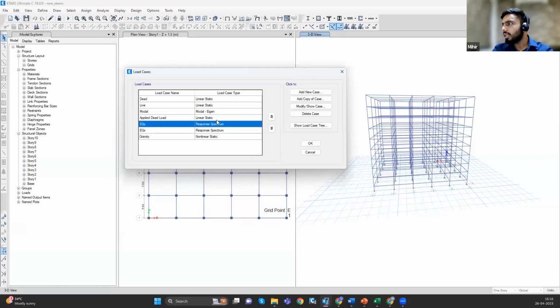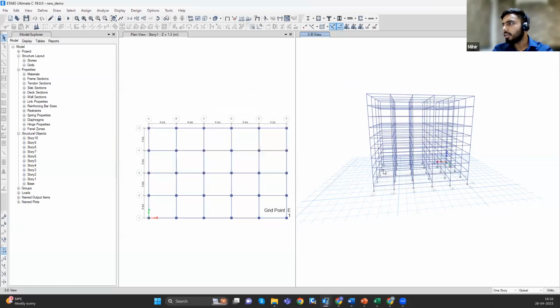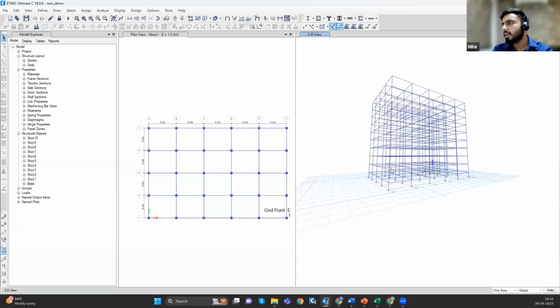So as of now, for the earthquake forces, I believe these columns are not passing, but I will move ahead for now. This will be an iteration process. We need to check how the structure is behaving, and accordingly we will update the member forces. But as of now, we will move towards the next part. That is the capacity, like how we are getting the pushover analysis done and how to define the hinges.